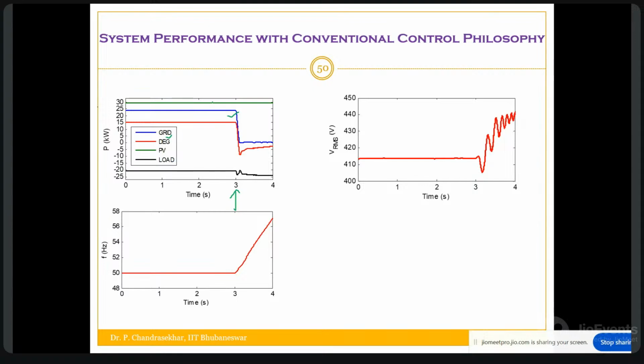As there is excess power of 25 kilowatts, suddenly the microgrid got isolated. Before the isolation, these 25 kilowatts were flowing into the grid. Suddenly the breaker has opened and the microgrid got islanded. So what will happen? Where will this 25 kilowatts go? Can this power go to the grid?